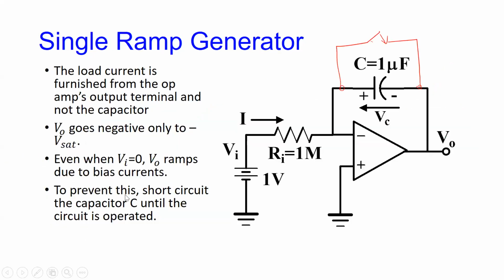And it's fairly easy to figure out how to hit. Notice this bit here. You need to know this always. Whenever you pick an op amp, if you're supplying it at plus or minus VCC, the op amp does not generally go to that. It goes to a close output, which is its saturated output.